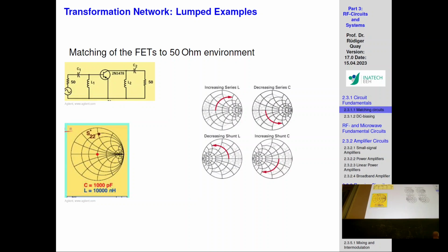Something like that. A certain capacitance, and this can be more or less neglected, but the main parts are the inductance and the resistance of the line that you apply. So the thickness of the line, how wide the line is and how long the line is. The length will define the inductance, and the width will define what kind of resistance it is, 50 ohm, 75 ohm line.